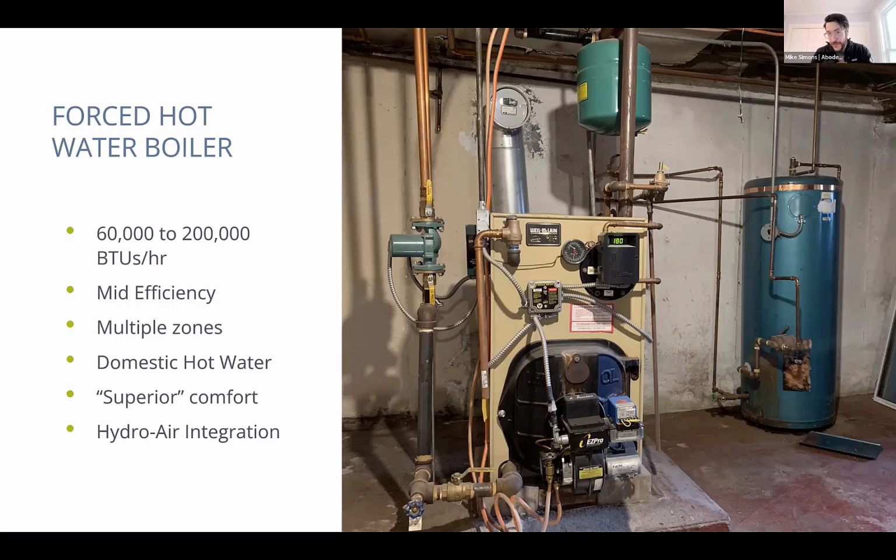So most of the time, if the home was properly designed for 180 degree water, they did an accurate heat load calculation and put in baseboards for 180 degree water. If you put in an air to water heat pump, that is not going to sufficiently heat the home.